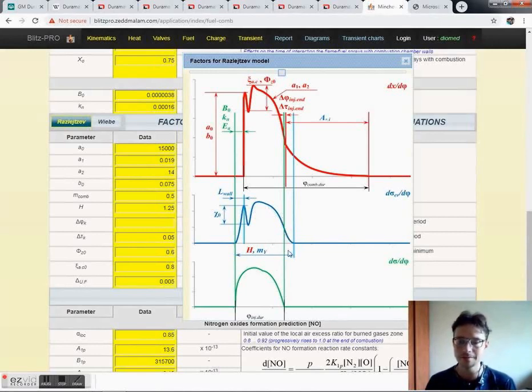The speed of evaporation, the time of evaporation, could be altered by applying the swirl ratio H and this multiplier My. And the drop in the speed of fuel evaporation due to interacting with cylinder walls could be set up with K0. Yeah, we made this setup before.